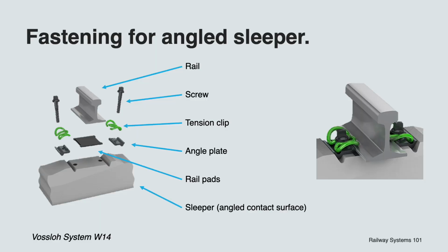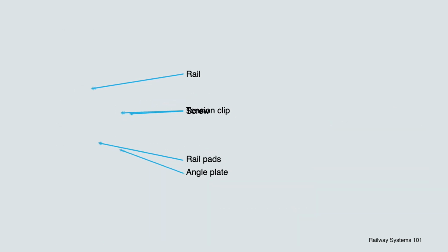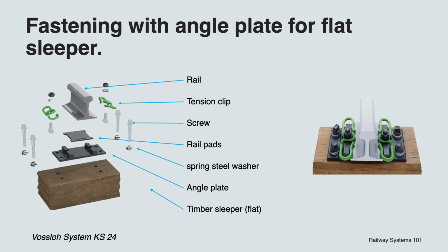Okay, let's wrap up what we just learned. In this lecture, we learned that stress from the rails is transferred to the sleeper to distribute the load on the ballast on the superstructure, from which material sleeper ties are made and their different features, that fastenings connect the rail to the sleepers to form a rigid track grid, and that the rail inclination is realized either with angular mounting points on the sleeper or with angular fastening plates.